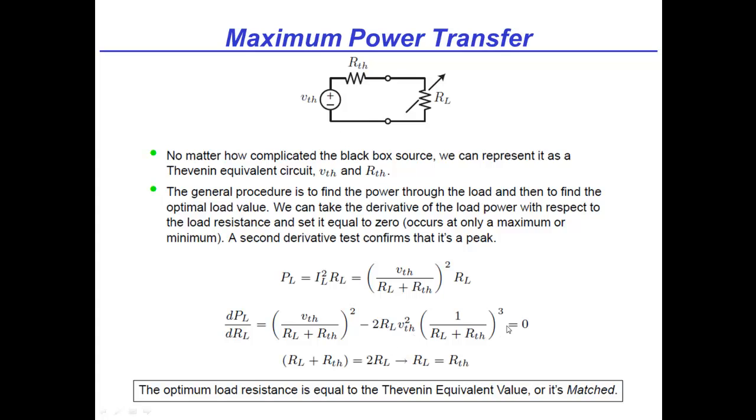So last thing I want to say before we move on is that this really finds its use in many, many places, not just, say, how to get the maximum actual power from a motor to a battery. In its more complex form, it finds its way into all sorts of radio frequency and antenna and communication applications. It's a really simple but fairly fundamental thing. And one example where even in the DC sense it matters is if you have a photovoltaic panel, a solar cell array on the roof of your house, there's an inverter there that takes the DC output of the solar cell array and drives it into the grid.